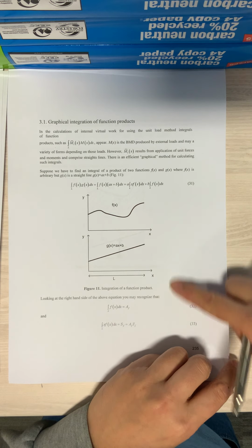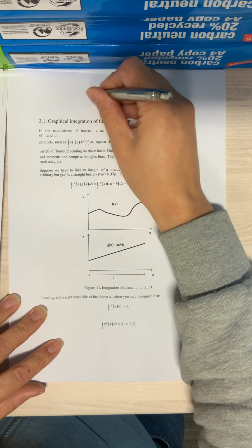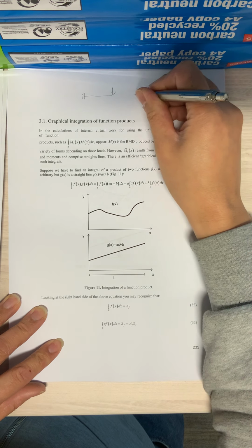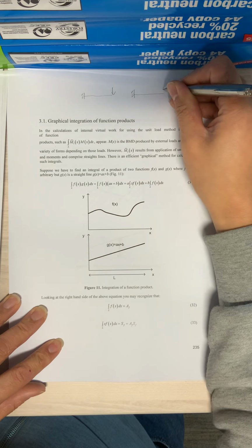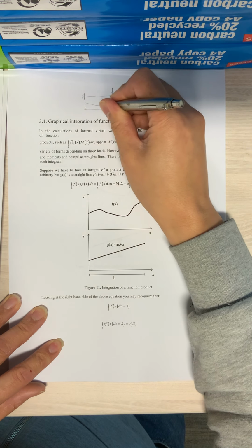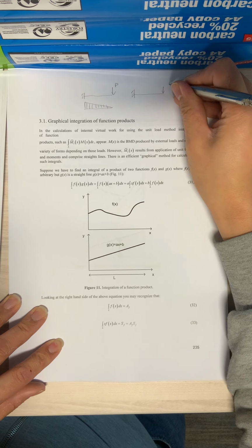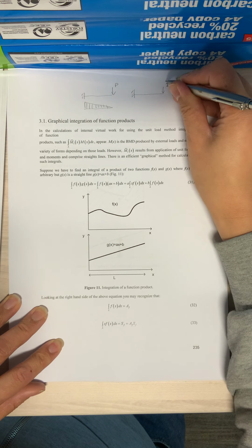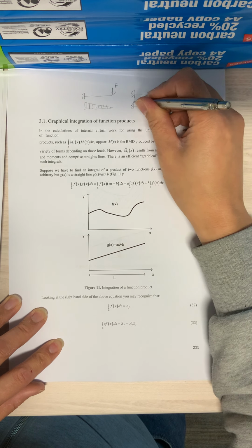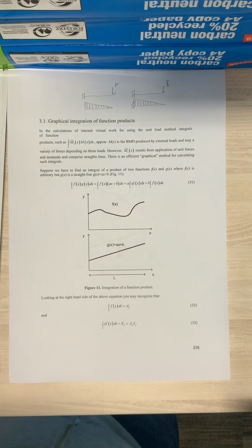how to graphically integrate, because we will be, for example, needing to, if you've got a cantilever and you've got another beam here, don't worry about this, I'll go through it in a second, but if you draw the bending moment diagram of that one there under a load P, and then here you had a virtual load, which I'll put a dash on top, you might want to be integrating these two functions when you multiply them together.